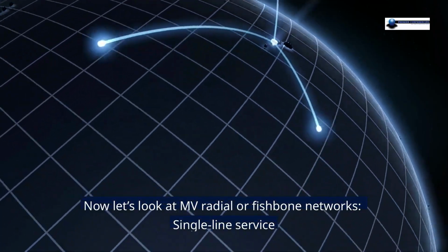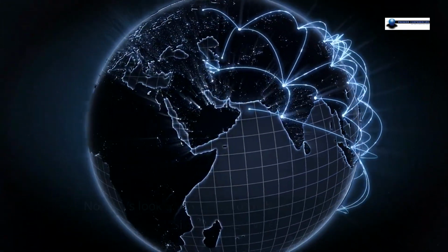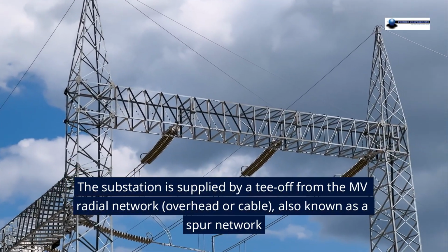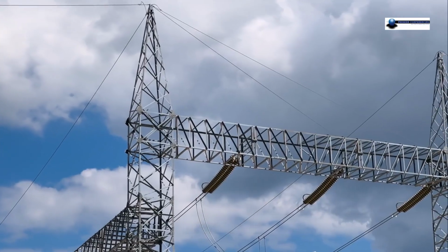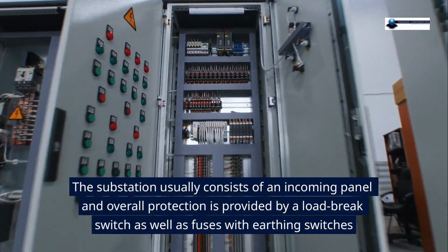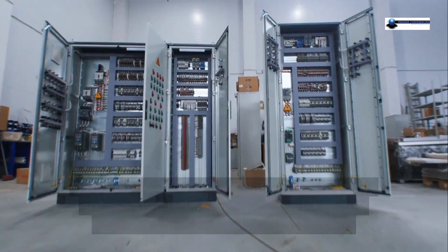Now let's look at MV radial or fishbone networks, single-line service. The substation is supplied by a tee-off from the MV radial network, overhead or cable, also known as a spur network. The substation usually consists of an incoming panel, and overall protection is provided by a load break switch as well as fuses with earthing switches.